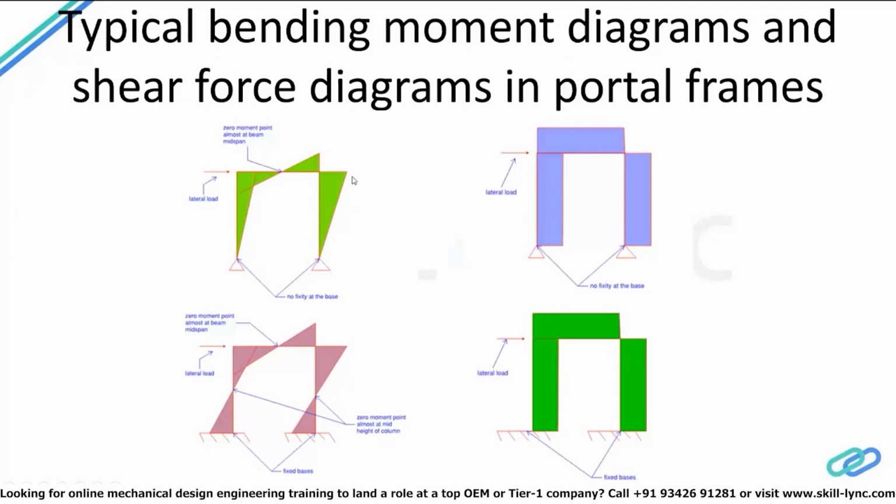And then once you move to this joint, if you see here, when you apply this lateral force, this is the bending moment that's developed in the beam, which is going from a negative value to a positive value with a constant slope over here, because there's a constant shear force that's acting on this beam, which we are seeing on this side over here. And then once you reach the column over here, you again see this bending moment in the column joint, and then as you go down at the pin, it reduces to zero, right?